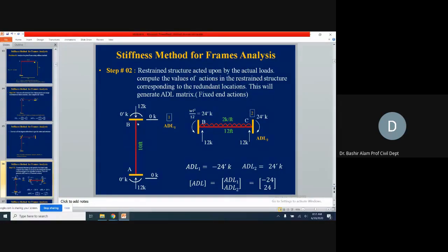Now remember, if there was some shear force in B in the horizontal direction, we did not stop the horizontal sliding here. So what will happen? From this joint B, in the opposite direction, it will shift to joint B of the BC member, and for the BC member, it is going to be balanced by this joint C force. Here you will have the opposite reaction, whatever you have on this B. So the member has to be in equilibrium. Maybe in the next problem, we are going to have this kind of situation.